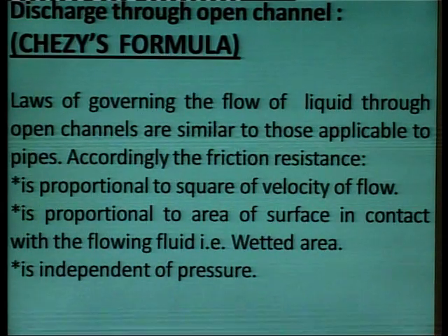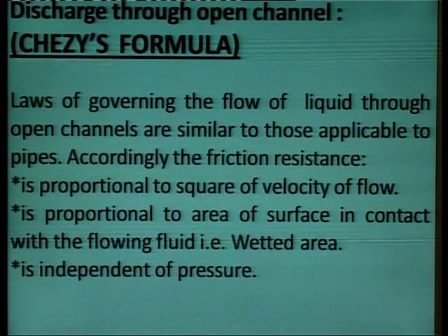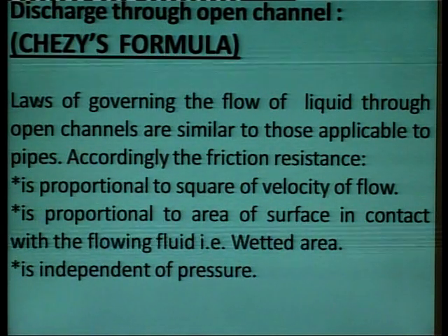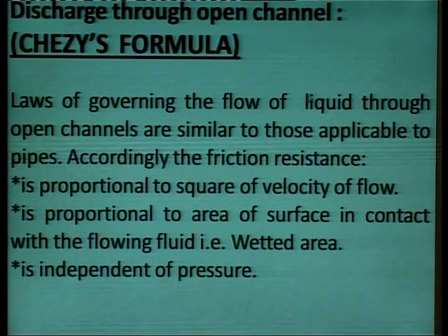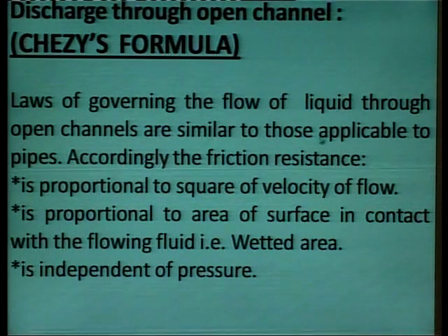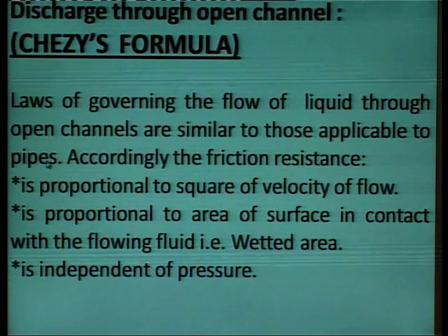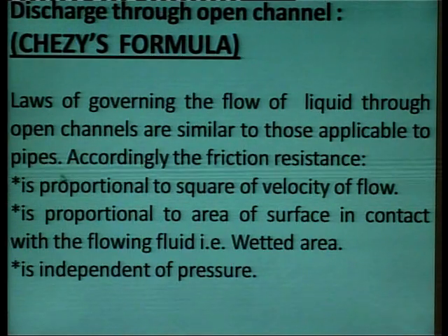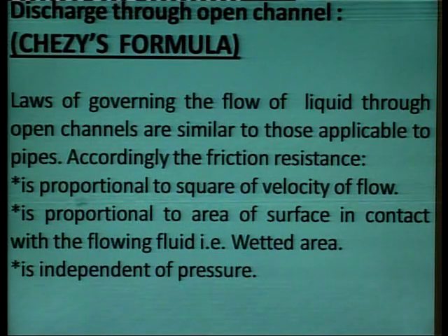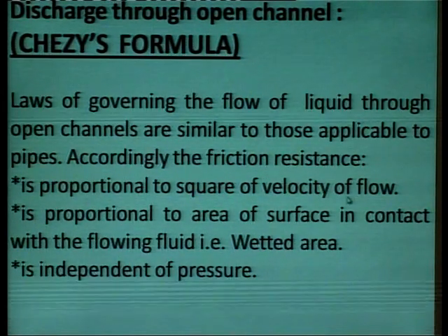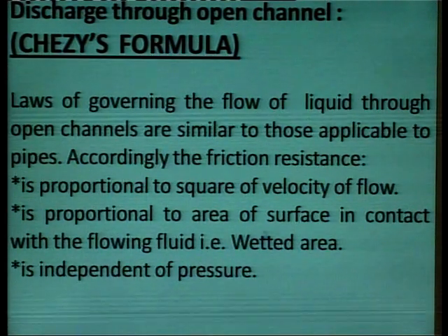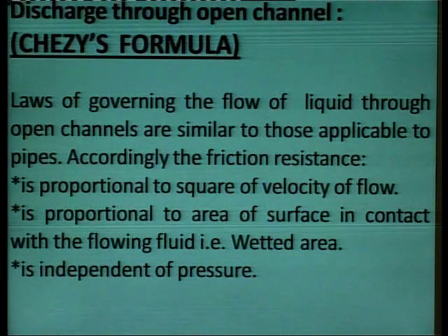Then the next topic is discharge through open channel. The first one is Chezy's formula. The laws governing the flow of liquid through open channels are similar to those applicable to pipes. According to these, the frictional resistance is proportional to the square of the velocity of the flow. It is proportional to the area of the surface in contact with the flow of the fluid, that is the wetted area. It is independent of the pressure.